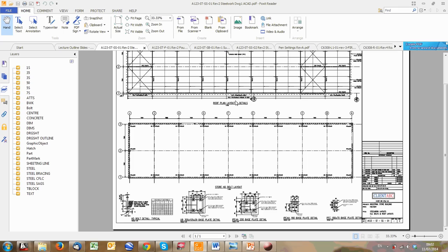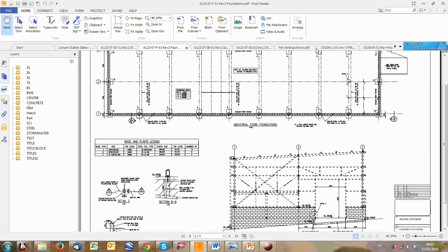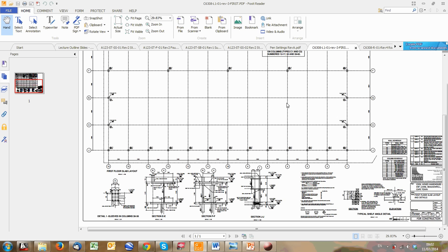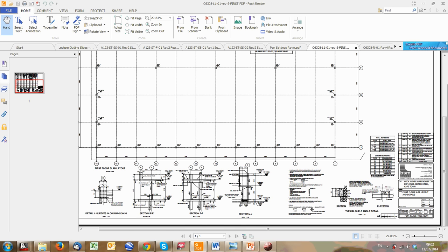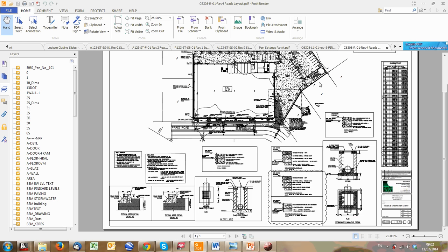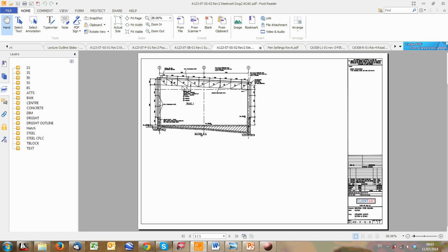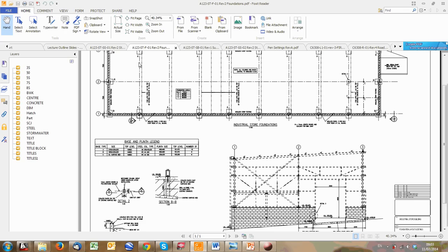So it is layouts, details, sections, specifications, schedules, any detail he requires to produce the structure safely. This is a roads drawing, so we'll have layerworks information, stormwater details, steel details, etc. You need to think about what information I need to put on this drawing such that if I was the contractor, I could build it.